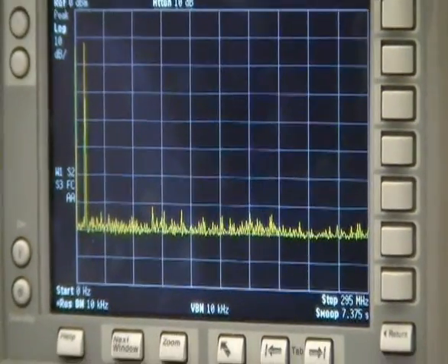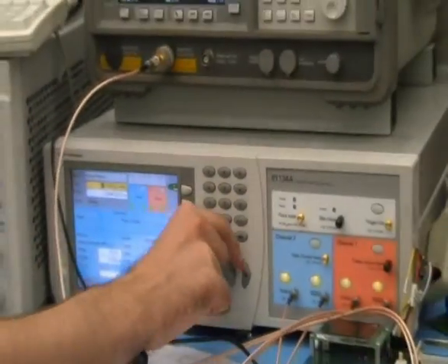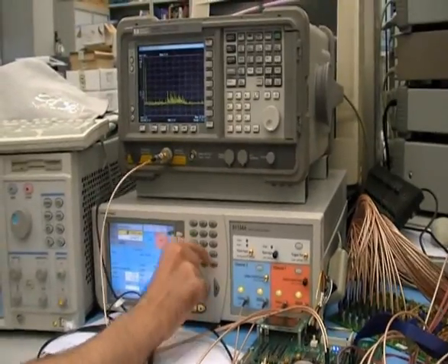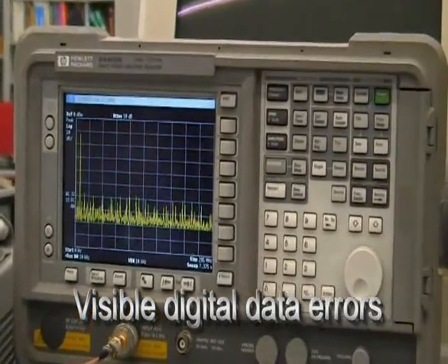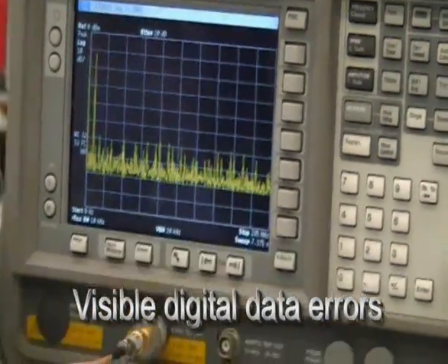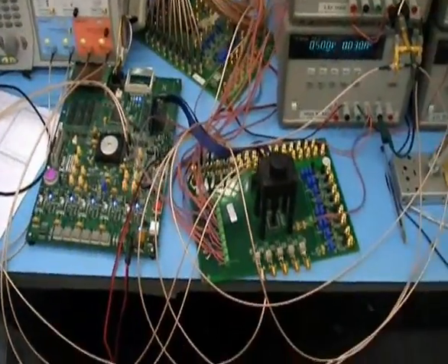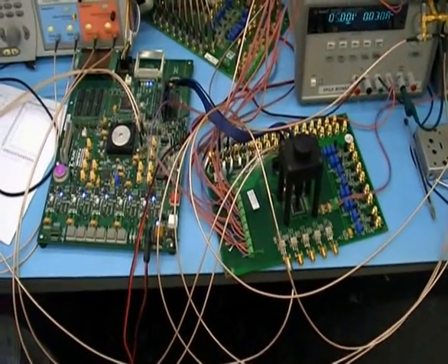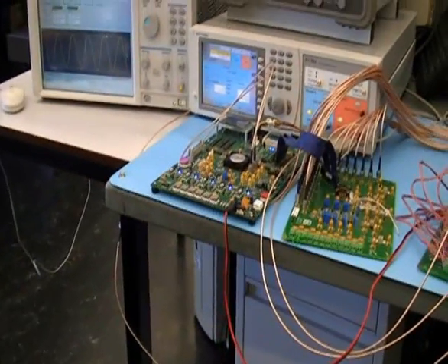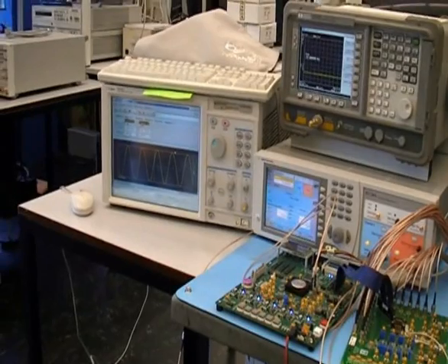What will happen if we increase further the sampling rate? I should show it. You get a lot of digital faults, these are digital errors. Some of the bits of the data cannot propagate properly and get into the test chip DAC. So in brief, you generate the digital data here, and you transfer it to the DAC, and then you measure the DAC. As simple as it is.